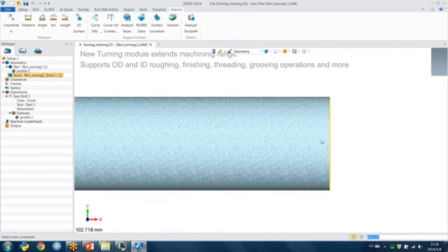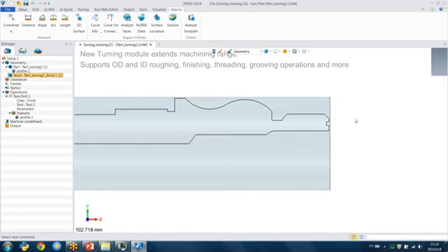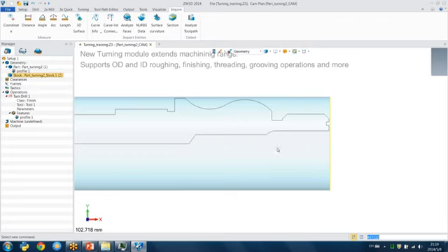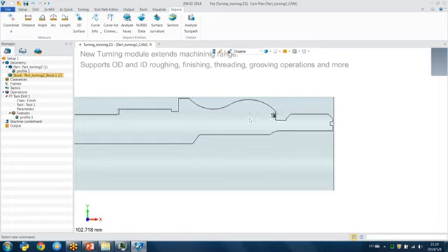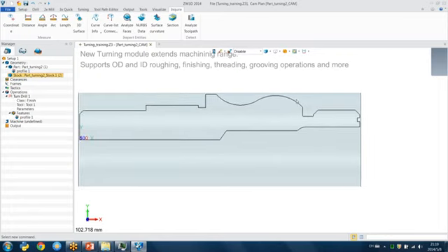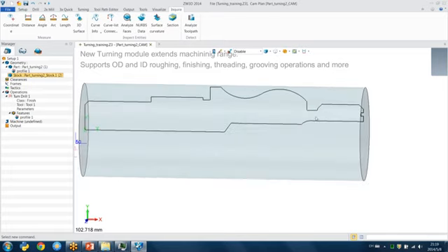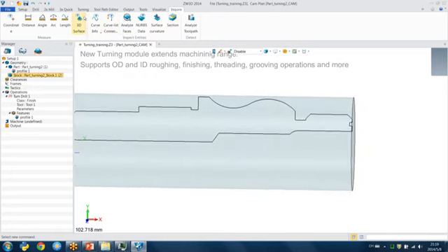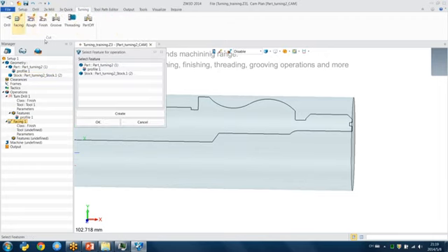Okay, show the stock. When using the CAM, you can change the filter to disable, so that when the mouse moves on the stock or profile, there is no highlight. Okay, so that's more clear. The next step is to do the facing. So I do the facing operation.